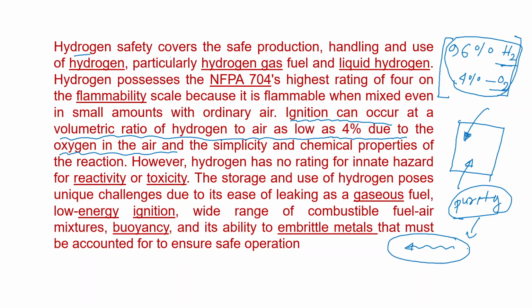So less than 4%, or less than 3% volumetric percentage of oxygen in the hydrogen is acceptable. Above 3% oxygen in the hydrogen-oxygen mixture is not acceptable. Okay.